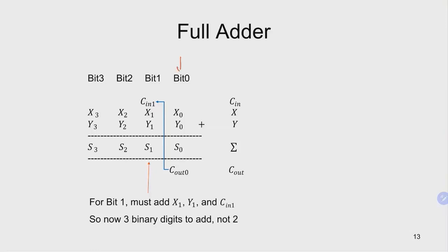So this bit here, just now, is a half adder. And now this bit here, we call a full adder. I'm not sure whether you have identified the difference between them, but I can simply illustrate this. In here, we only have 2 inputs, x0 and y0. In our binary number, we still have two inputs, x1, y1, in this bit 1 calculation, but we have an additional input that comes from the previous calculation. So now we have three inputs into our system.